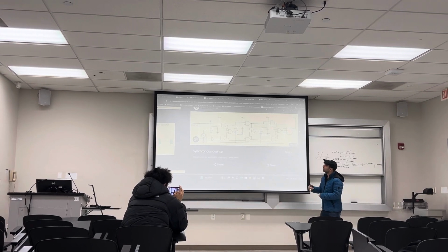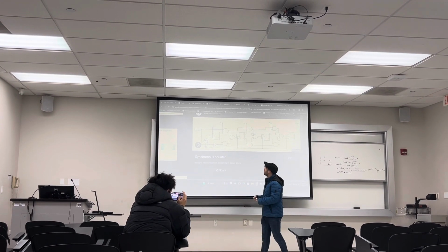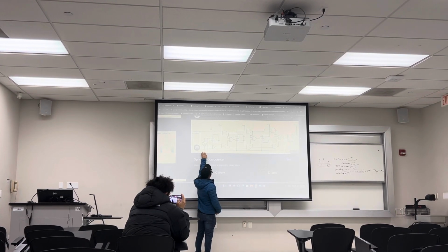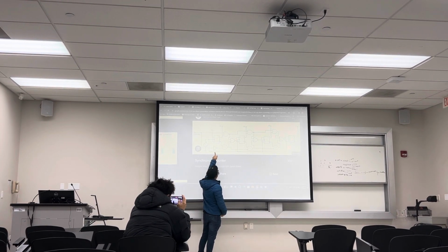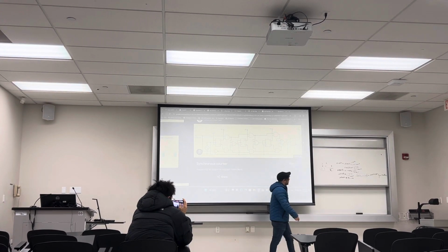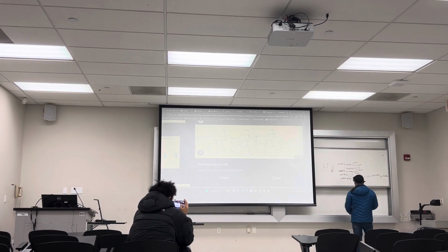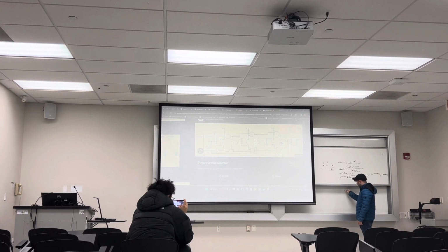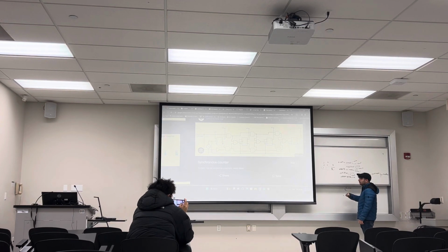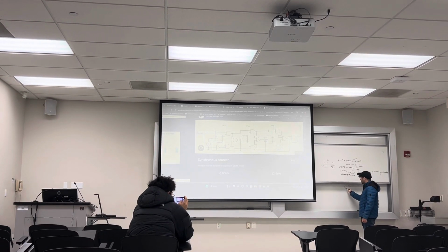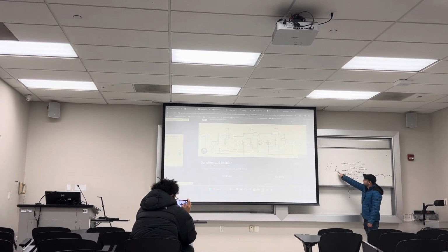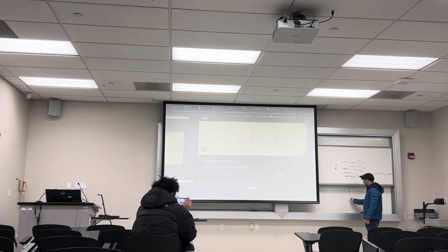So every time the clock goes to the circuit, look, this is the clock, a V pulse. The V pulse goes to the clock of the JK flip-flop, and every time the clock comes, the output will change. So if you see the output of the first JK flip-flop, Q0, every time the clock comes, the output will change. For example, if it's 0, then at the next clock it will be 1, the next clock it will be 0, because it changes every time. 1, 0, 1.